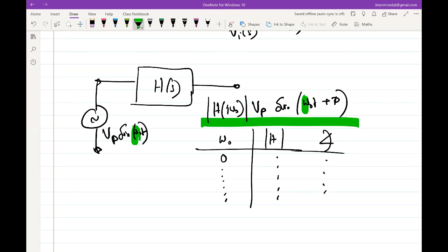Right? Omega is what you are varying. Physically, when you are tuning the frequency, you are varying omega. You are not varying sigma. Sigma is not in your control, which means that you might not have a 0 at a particular value of omega, but you can have a 0 at some value of s. They are not the same things. Correct? So experimentally, you will probably not be able to find the location of the 0 because you can only vary omega.